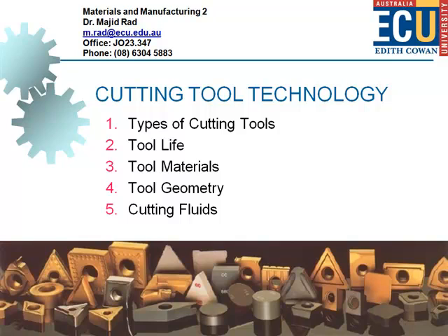When we are replacing the cutting tool, we've got to pay for the time of replacement, for the time when the machine is not being used. It's not making money. And once the cutting tool is replaced, we have already paid for the new tool, despite the fact that if we had used the previous tool properly, we would still be using the older cutting tool, which would reduce our cost eventually.